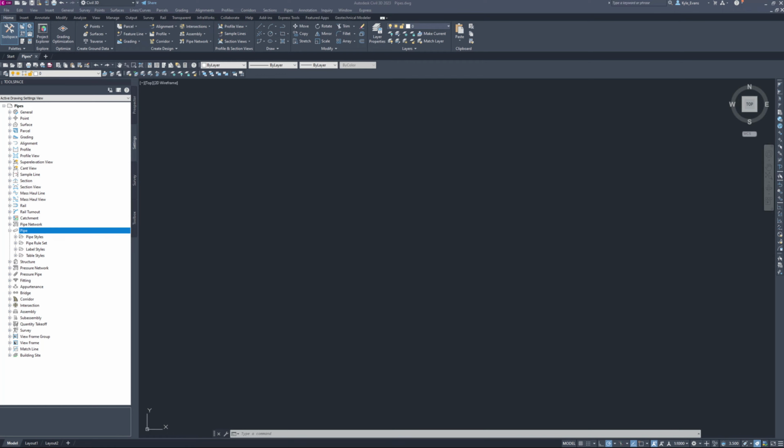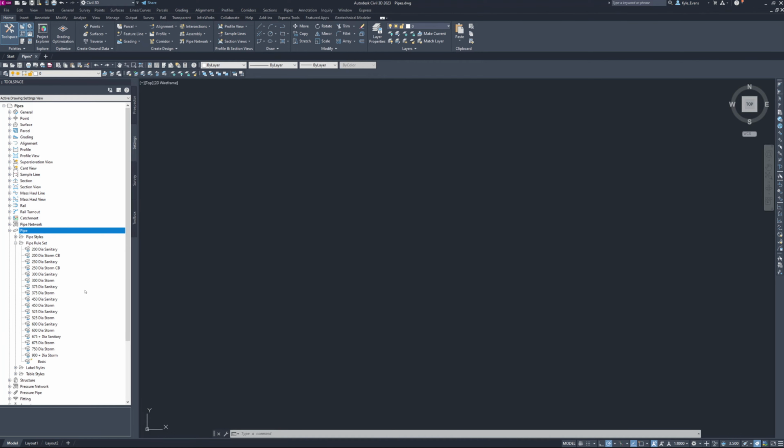In the previous video we took a look at our pipe rule sets, specifically in regards to sanitary and storm. Now I haven't created a water parts list because I'm going to be doing that through the pressure networks that are built into Civil 3D. We have only done it for the gravity drain systems here. We have everything from 200 to 900 plus diameter storm.